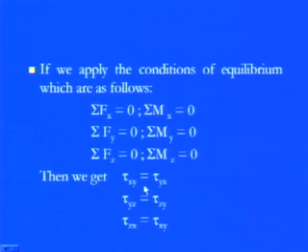So if you are talking about those things, then we can say that tau xy is exactly equal to tau yx, because if you are talking about the frontal part and if you are talking about the rear part, they have the symmetricity and there is no change in the force. We can say whatever the parallel forces are there which are being set up in two different domains as well as the two different directions, they are equal because they are equal and opposite. That is why we can say that the summation of forces are equal. So similarly, if we apply this symmetricity to this object, we can say tau xy equals tau yx, tau yz equals tau zy, and tau zx equals tau xz.